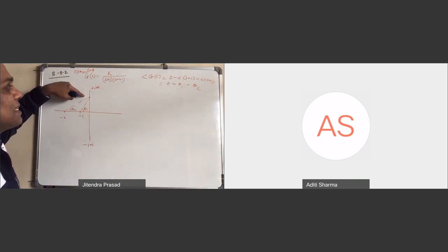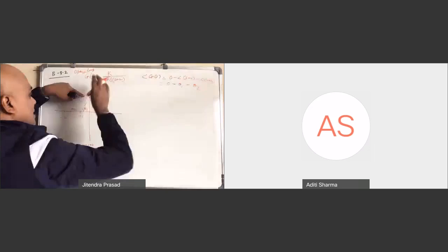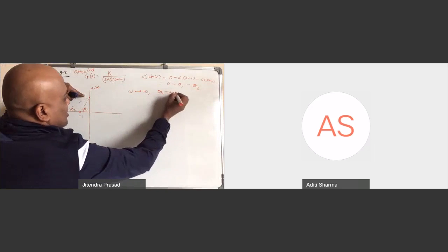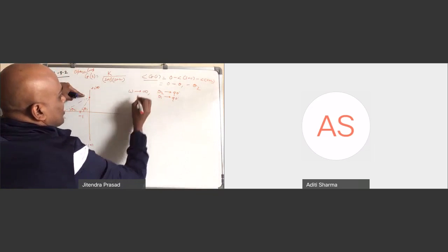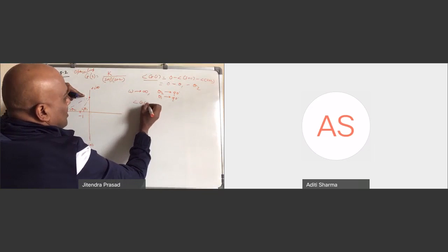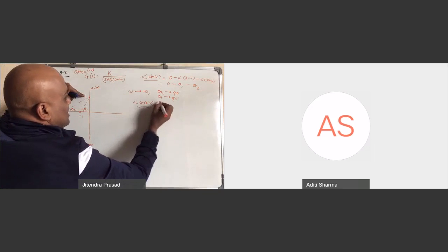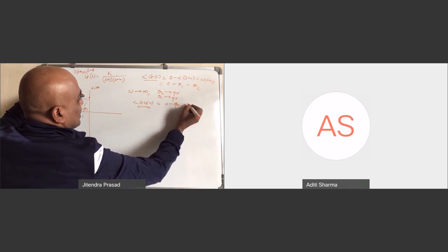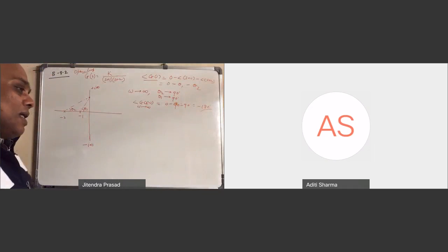And then you see that when omega tends to infinity, if this point is far, far away above, then θ2 tends to 90 degrees, and θ1 also tends to 90 degrees. Hence, the angle of G(jω) as omega tends to infinity becomes 0 minus 90 degrees minus 90 degrees, equal to minus 180 degrees. So you can relate from there also. Always try to verify with different methods.